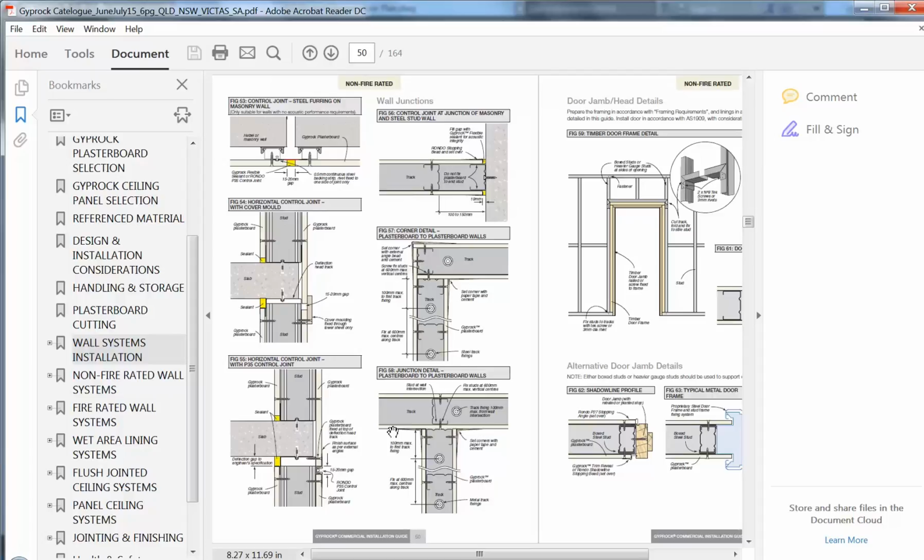Yeah, that's right. But look, you could show studs in your 1 to 50 floor plan, and they would come up pretty clearly. But all of the other detail there, definitely 1 to 10 or 1 to 5. But again, you need to specify it somewhere. So if you're not going to show it in your plans, which I would probably recommend, as it's too complicated to show all of this in your floor plan, make sure you indicate it in your specification.